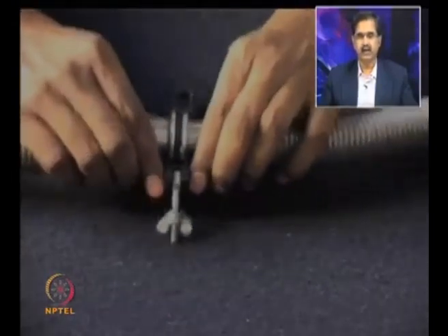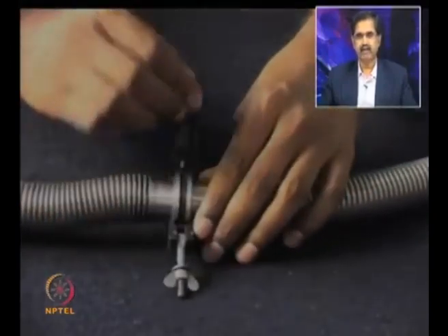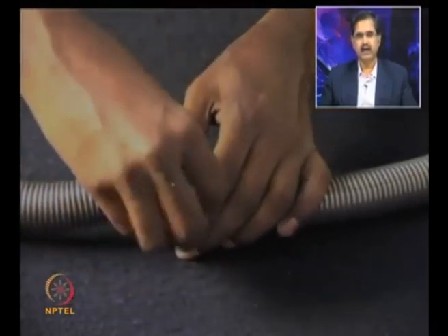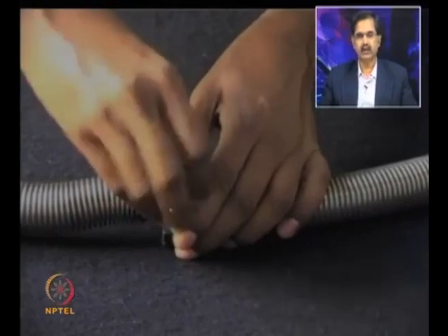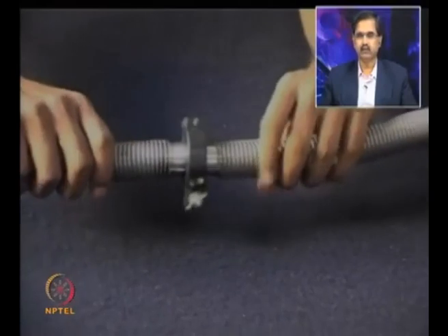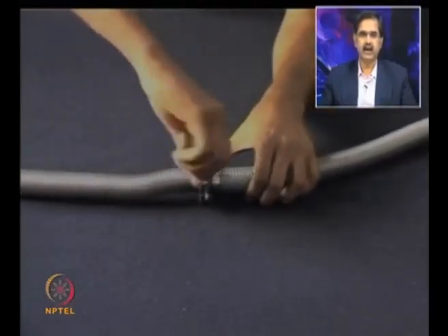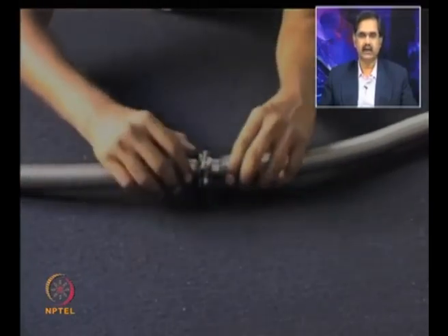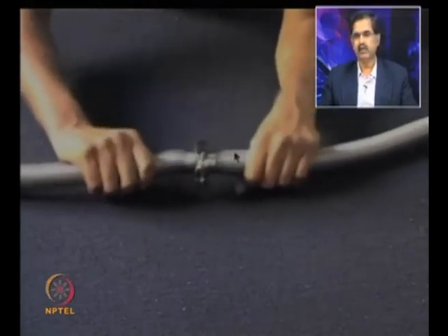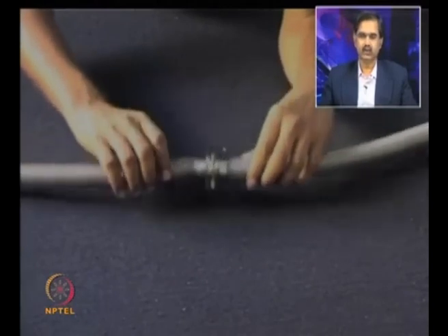So, this is the way a KF coupling would be assembled, and this is what will be used everywhere in all the cryogenic experiments. And therefore, the conductance of the entire connection will change because you have two lengths brought together for various reasons. This is the way two hoses of 1 meter lengths will be connected. At one end you have a pump, and at the other end you have, let us say, some vacuum jacket, of which you have to take a vacuum basically. And this is the way the two vacuum hoses will be connected without any leak, with a perfect sealing mechanism.